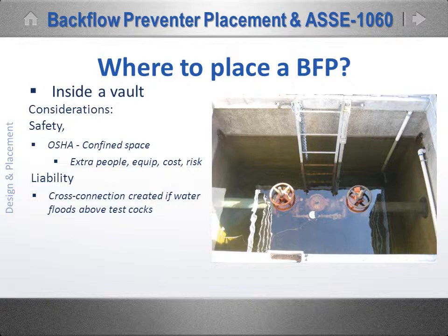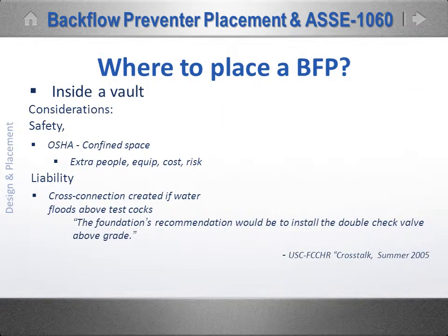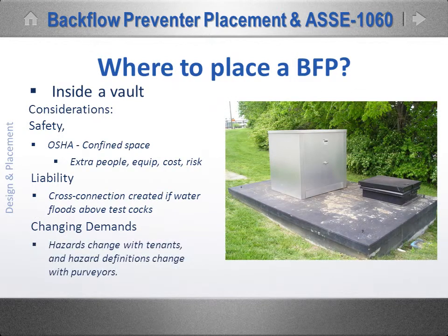In fact, it led the USC Foundation of Cross-Connection and Hydraulic Research in 2005 to change their recommendation of even double-check backflow preventer installations in vaults. They said the Foundation's recommendation would be to install the double-check valve above grade. Finally, changing demands.